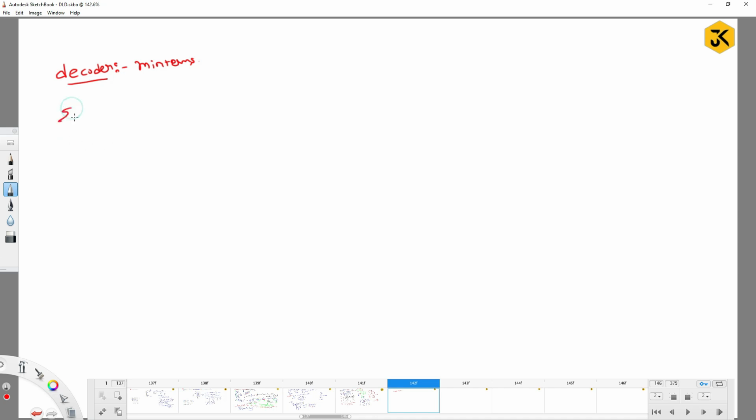For example, if my Boolean function contains the minterms 0, 2, how are we going to construct it? What kind of decoder is required? Is a 1x2 decoder enough? No, because you require a 2x4 decoder. The reason is when you have 0 and 1, you require only a 1x2 decoder, but here the outputs are 0, 2, ranging from 0 to 3. So that's why you need to go for a 2x4 decoder. So here you are going to have 2 inputs and 4 respective outputs.